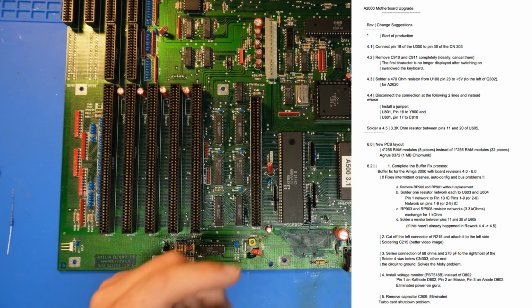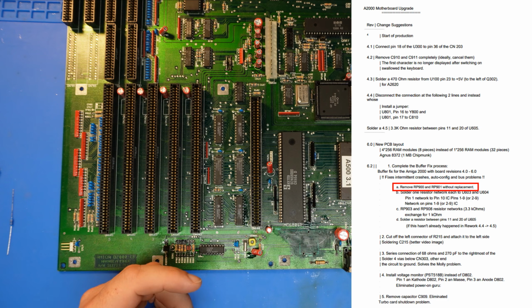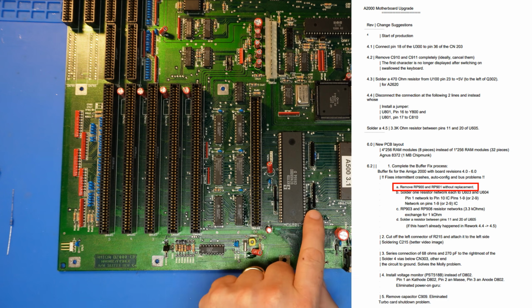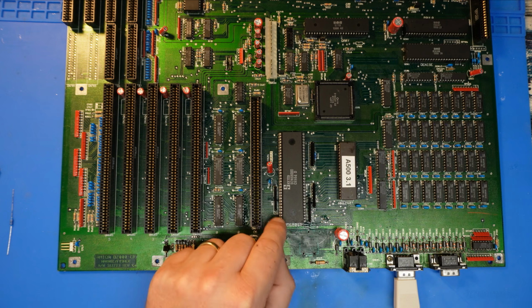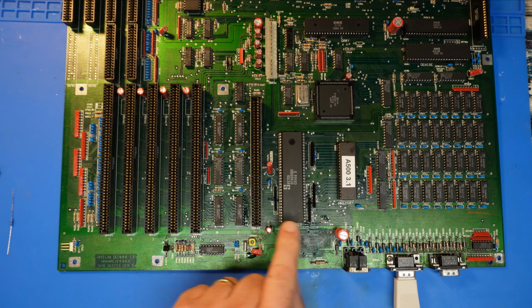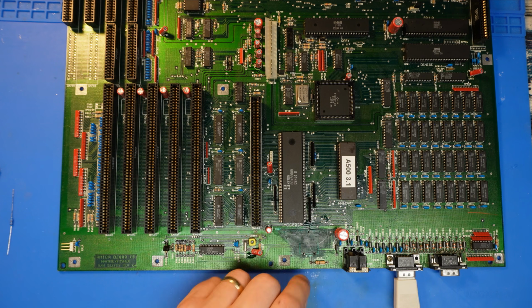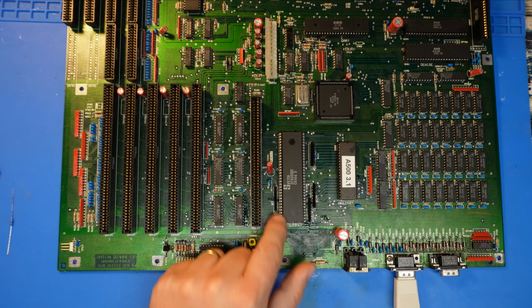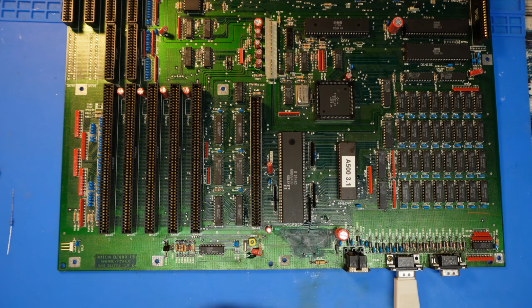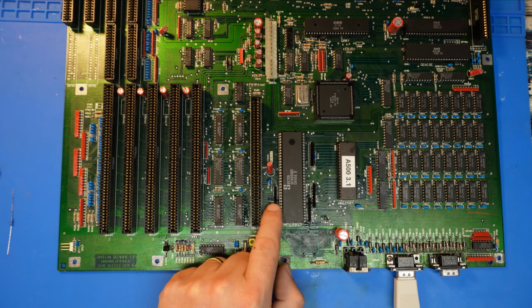And if we go down to 6.2 then, the first thing that we need to do is remove resistor packs 900 and 901. That is those two 10Ks that we fitted last time. But because of the amount of repair work that's been done around these, and in fact through these, if you remember some of the holes through the board where those resistor packs fitted, they were damaged and we had to put lots of little wires in. So to save any potential of me undoing some of that repair work by trying to desolder these, I'm just going to cut them out.